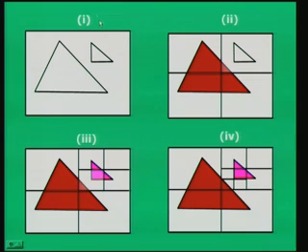An average case can of course be computed, but average is very difficult to compute because it all depends upon the number of triangles or polygons which you have, the relative positions of those polygons, the relative positions of those edges and vertices. The closer you have the edges and vertices of 2 different polygons together, or overlapping more, the more subdivision you will have, and that is where you need to spend more time. As you can see here, when you compare stage 1 initial stage and stage 4 final stage, the subdivision is somewhere around here, where there is a bit more overlap.